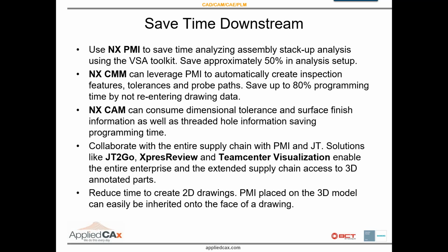And you can collaborate with the entire supply chain using PMI and JT with solutions like JT2Go, Express Review, and Teamcenter Visualization. Those are Siemens products. JT2Go and Express Review are free, while Teamcenter Visualization is a licensed tool and has a lot more capability. There's other tools out on the market as well. I'm not going to cover them in this webinar, but just a Google search, you can find a lot of JT-related tools. In fact, starting in Windows 8, JTs can be visualized just in Windows. You can reduce the time to create 2D drawings by placing PMI that's been placed on a 3D model into the drawing.